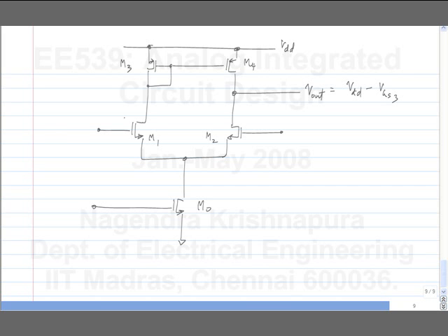And let us say it is in the quiescent condition. What do I mean by common mode gain? I apply an equal increment, that is, in-phase increments to the two sides, and look at what the output increment is. Right? So, what do you think it is? How much is the common mode gain of this? Yeah, that's correct. 1 by GM3.